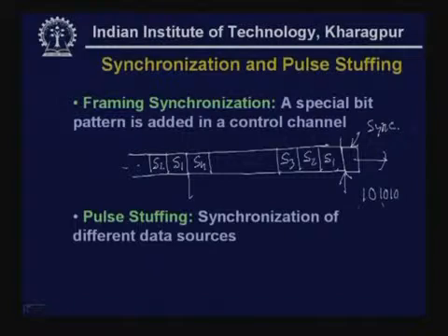So, you may send 8 bits of 1 0 1 0 1 0 1 0 that forms the synchronization character, and after this is detected at the receiving end, subsequent slots are for different data. So, this is considered a channel, say channel 1, this is again channel 1. In this way channel 1 is repeated.